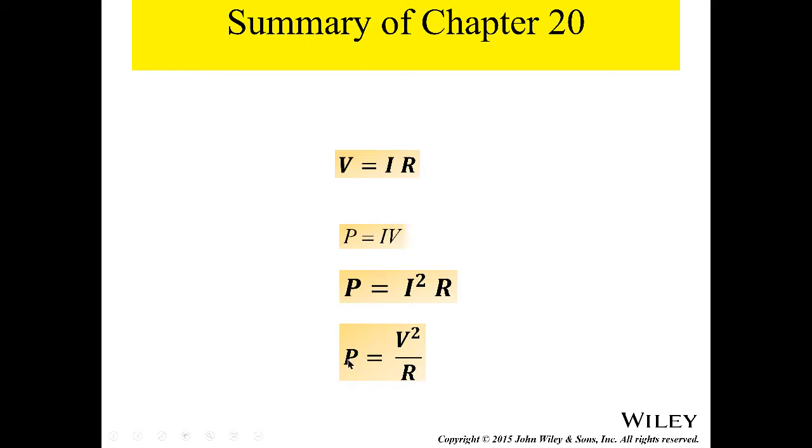It's already rated, and you are using it in the United States, where the voltage is 120 volts, so it is another way of saying what the resistance is. Because the resistance is V squared over power, and you know the voltage and you know the rating, you say, oh, the resistance is 7.5 ohms.